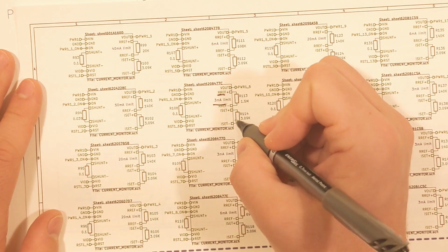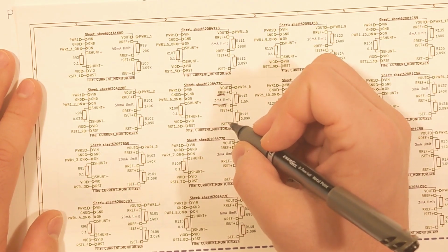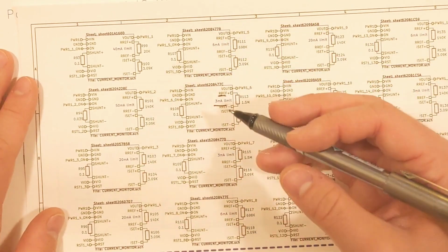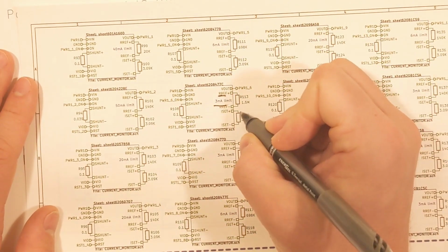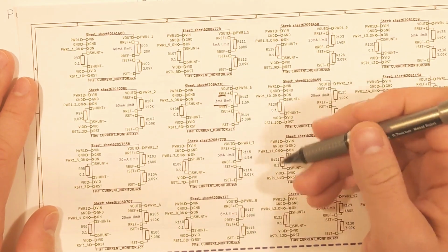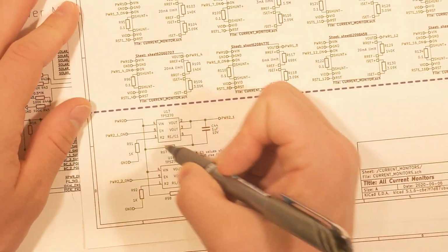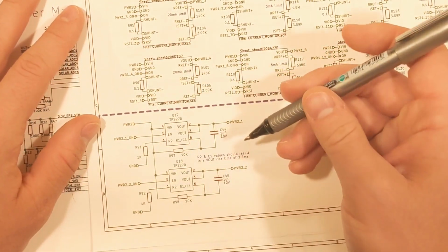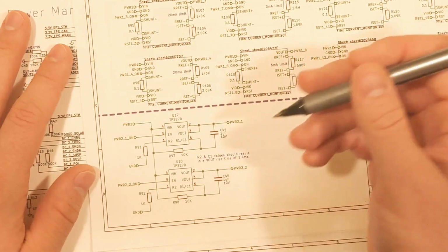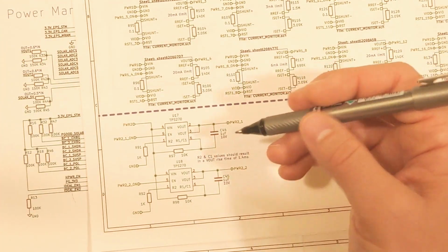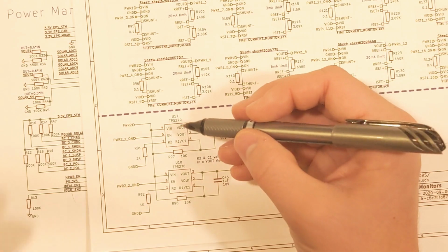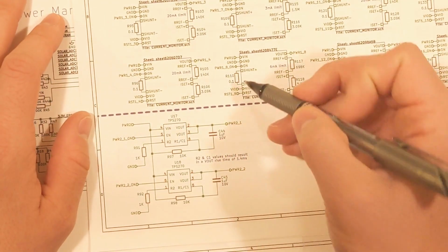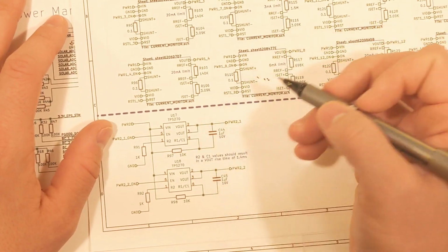And then this I set here is for the load switch I use inside, which is the same FPF1213, which I showed you on the battery heater page, and I set the maximum current for this guy as well. Then under this dotted blue line, these are the quote-unquote high power circuits. So these are the 5 volt output. So in theory, I could have 2 amps coming out of that 5 volt converter. So I have these load switches, these TPS 270s, which are actually different from the load switches I use inside of each of these current monitors.